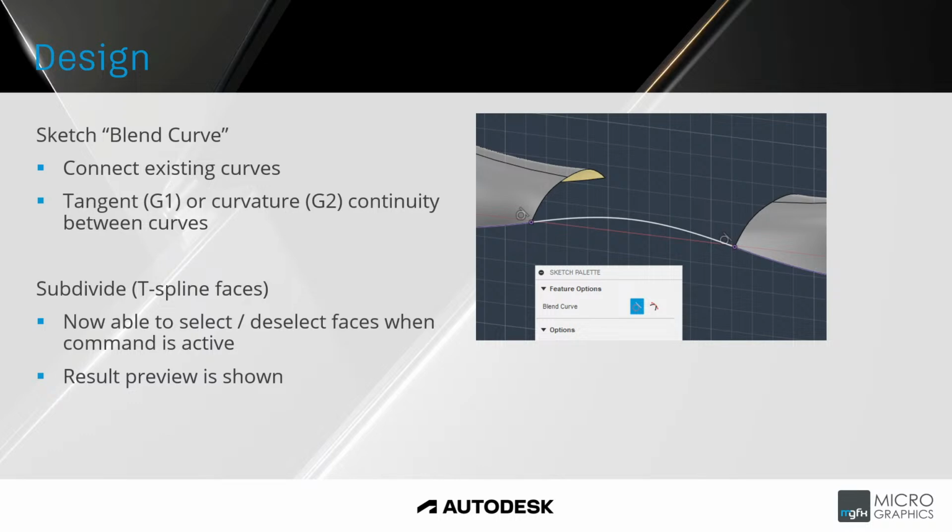So that image on the right hand side there, we'll see this in a demo that I'll do a little bit later on, but we've got two existing surfaces and we need to bridge the gap between. That blend curve can be added by selecting the edges of the surfaces and that blend connecting those two existing curves. Somewhat like a bridge curve in other software as well.